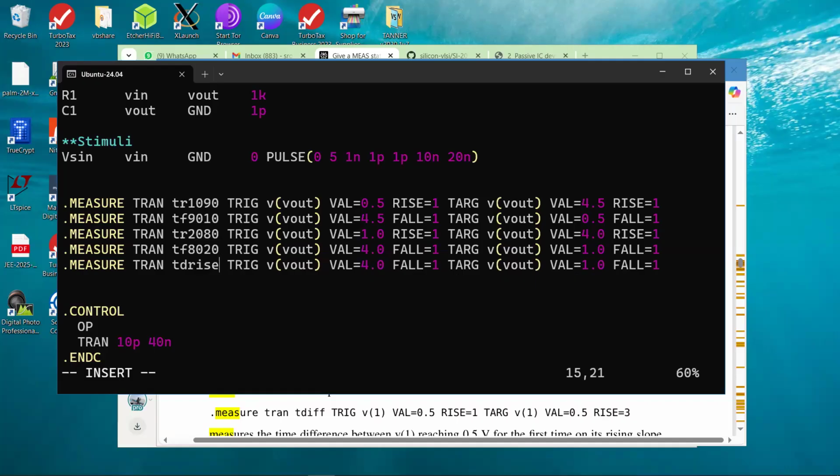Well, if it is perfectly, if it is a fast rising one, then it doesn't matter where you do it, it'll be the same. But since this is a slow one, so 50% is usually what you will take. Because see, if you take 90%, any small error on the top will get magnified. Again, this is not like a theory, but depends on the application, but that's typically what you would do.